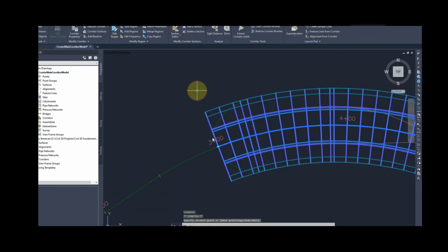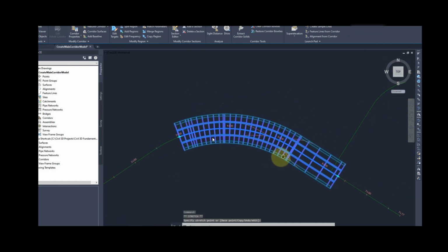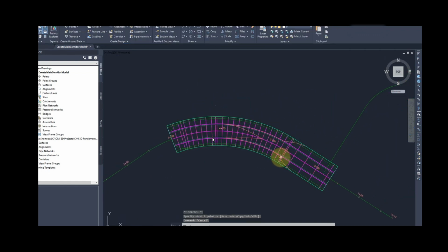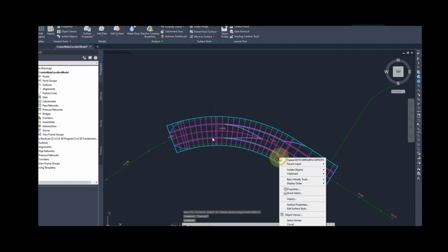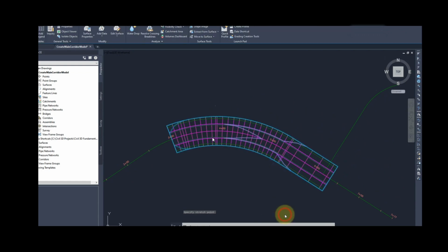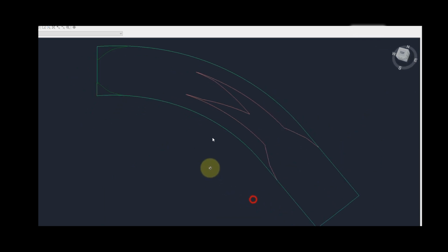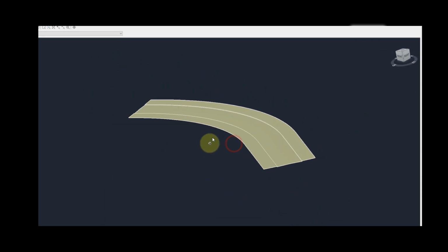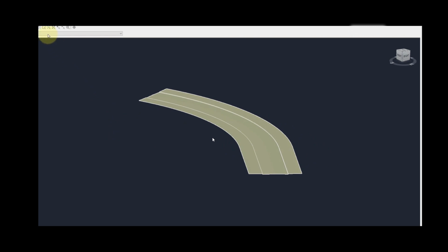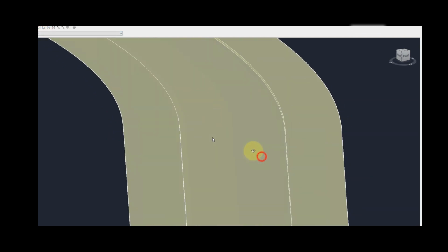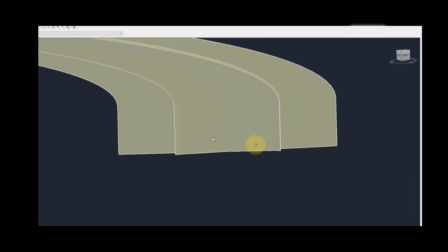When you are finished with your driveway corridor model, validate the corridor top surface. Select the corridor surface, then open the object viewer. In the object viewer, pitch and rotate your corridor model to validate the key break lines, like the crown of the roadway and the curb gutter details. You will frequently use the object viewer to validate your driveway grading as you progress in this workflow.